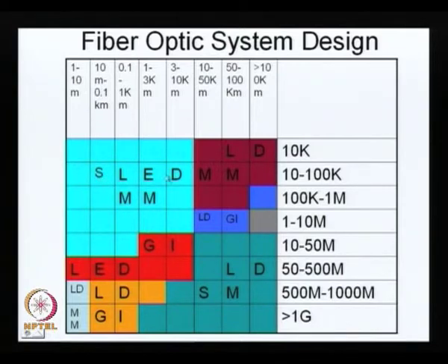So here we are having SLED, which is surface light emitting diode, and a multimode fiber. Recall, multimode fiber has a large dispersion. So this can essentially work for low data rates and also can work only over very short distances. So a surface LED and multimode fiber combination is a good combination for something like local area networks, because the kind of things which you are talking about are the low data rates on Ethernet kind of structures, and where distances also are small on local areas. So this is a good combination.